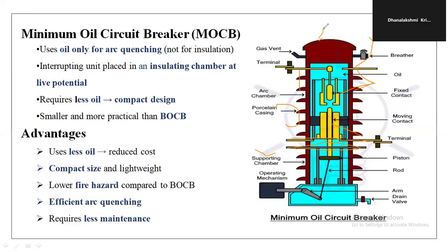It's a metal chamber and it's mounted on the circuit breaking chamber. It provides expansion space for the oil in the circuit breaking component. The top chamber is also provided with separators which prevent any loss of oil by centrifugal action caused by the circuit breaker operating during fault conditions. The operation is the same as that of the bulk oil circuit breaker.